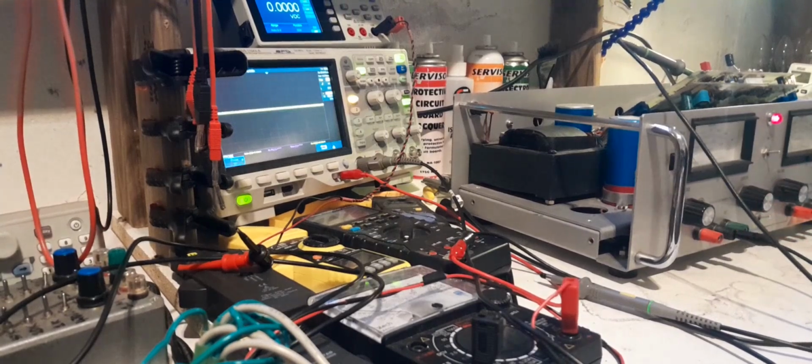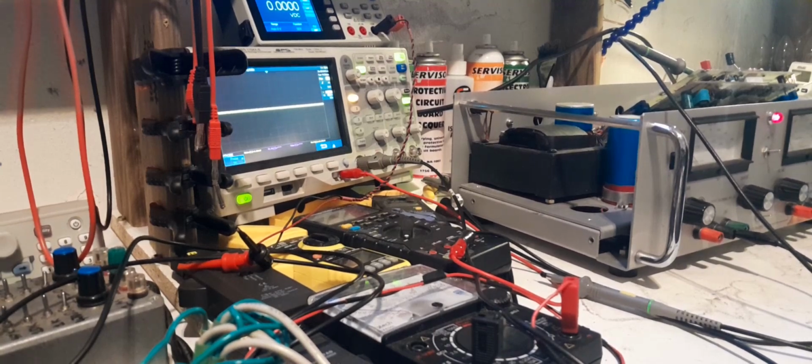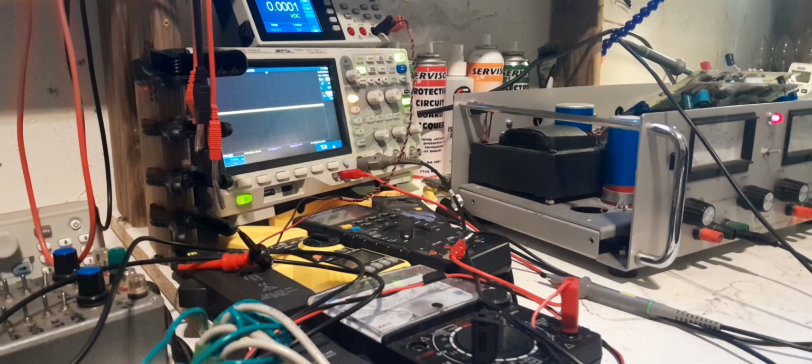Oh, and trying to put a snubber or a compensation network from the op amp's input pins across each other, that only couples the noise from one input to the other and makes it literally a million times worse. The TL431, I tried decoupling its reference pin. As I was saying earlier on, or in my last video, I don't know if I finished explaining what I was saying because I just waft off topic all the time. It's something I'm good at, but I've got a bit of experience playing around with switches and stuff like that, and a lot of times, I'll just grab one just to show you what I'm talking about.